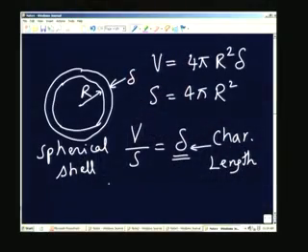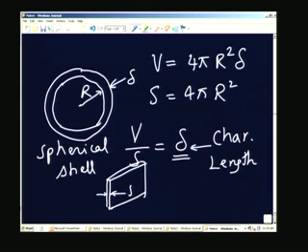In fact, I can also take the object in the form of a thin film of very small thickness like this. It has got two surfaces, one on this side and one on the right side. That is, the total area is the two surface areas, and the volume is the surface area multiplied by small thickness. So, again the thickness, if it is delta, the characteristic dimension becomes actually equal to delta by 2. So, I will say L_CH equal to, because there are two surface areas and the volume is proportional to surface area multiplied with thickness, therefore, I get delta by 2.